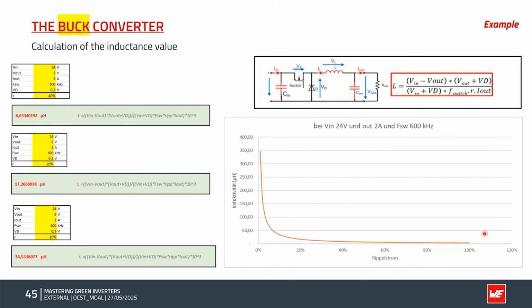And that shows us that 1 over R, which is a 1 over X type relationship. So actually, if you're going to really reduce your ripple percentage, you have to suffer a lot with a lot of inductance value in order to achieve that. So the moral behind this slide is the usual or default value that we usually go to is 20 to 40% as a ripple factor.